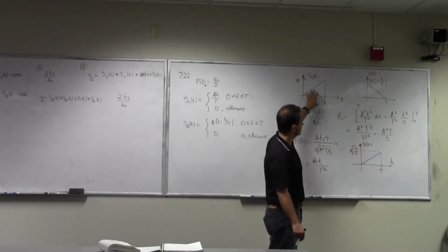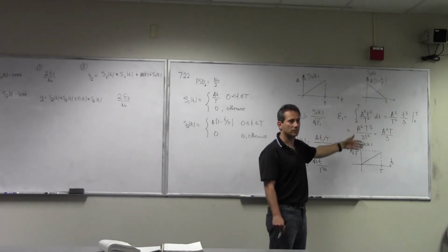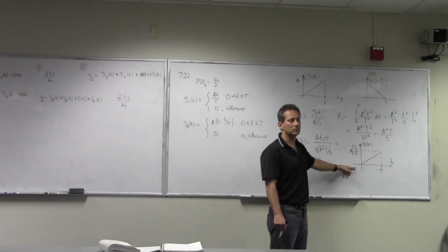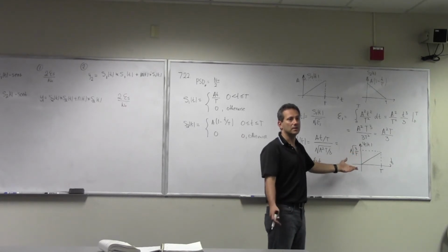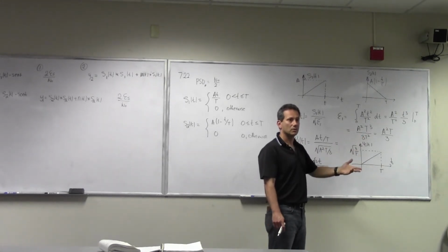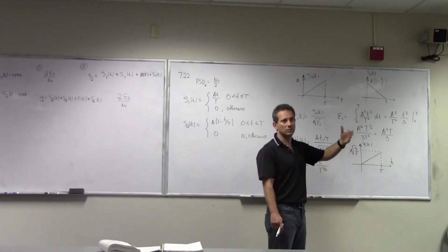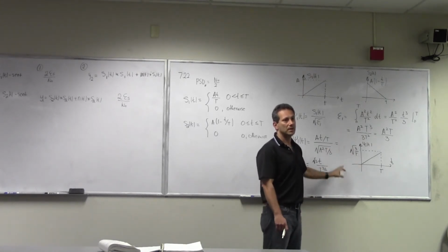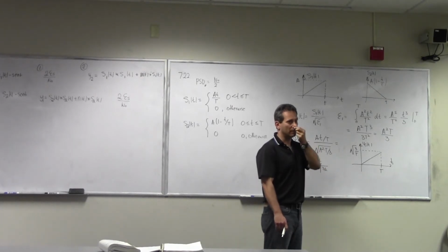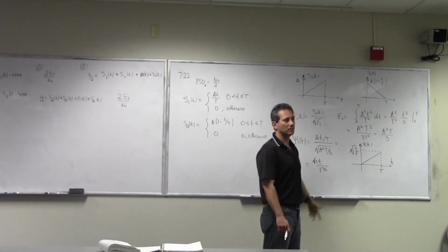Then the first is this, and the second is expressed in terms of two other orthogonal vectors. Then I'm done, because I know that the output of each one of them is square root of 2 epsilon s over n0. I already calculated, because this ends up being two-dimensional signaling, that the probability of error is Q of square root of s and I. So I'm done as soon as I decompose this into two orthogonal vectors. And I know that this is an optimal way. It cannot be better than that.